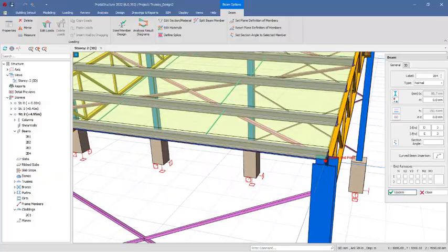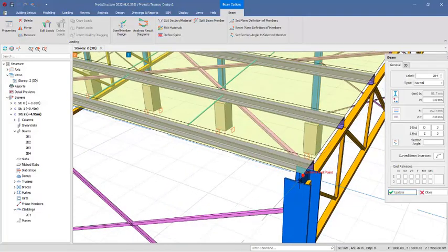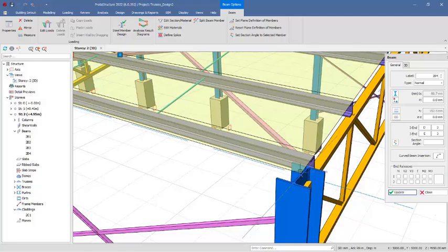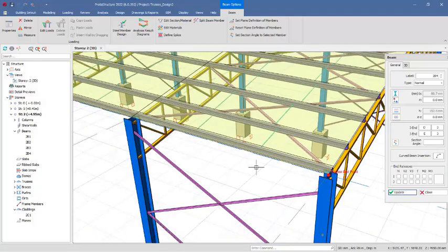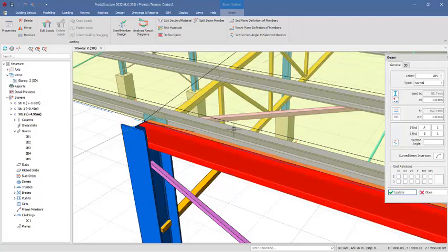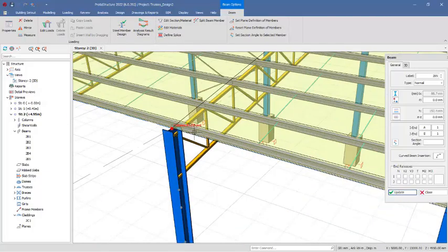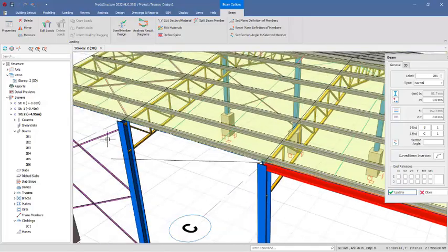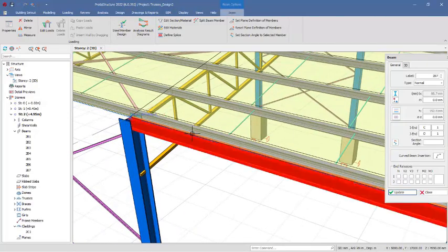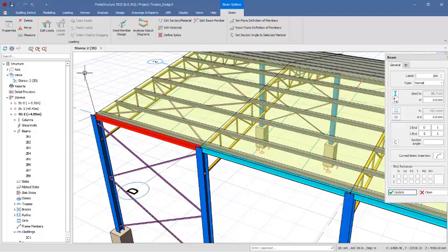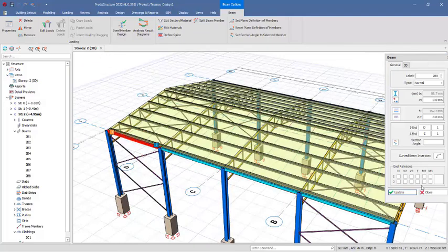So we get to this other side. So we pick the first one. You make sure you zoom closely and get the node point. The exact node point will actually show you the star right there. I see a green star and not the red dot. Okay, come over here. Once you see a green star, you click like this, click. All right, that is the exact point of the node. So you must make sure that you are careful not to misplace the beam off the node. All right, just like this. All right, so having placed this successfully, close this dialog right there.